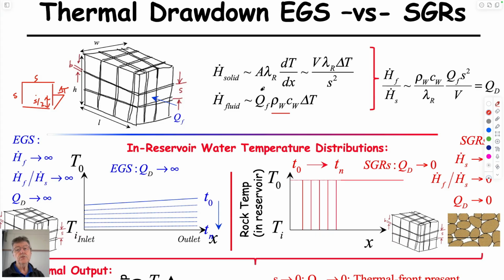And so what you could do is write Fourier's law. So the area over which it flows, so I guess the simpler way to look at this block would be to think of it as a length here, which is the spacing, a temperature gradient here, which is delta T. And so this delta X is really S over 2 because it would be coming from the center of the block, but let's not worry about that. And this is thermal conductivity, and then this is the cross-sectional area of flow.